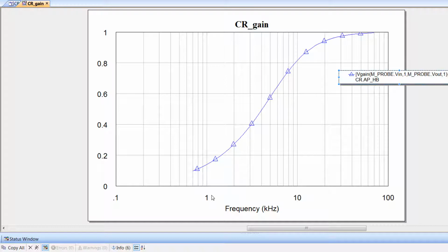Also, you can now see what I meant by a logarithmic scale and a decade. A decade is basically a difference of a power of 10. So we go from 1 to 10, from 10 to 100, etc. And within each decade, normally in the lab, you only measure where there is a vertical line. So you only measure about 10 points per decade. This is how a frequency response is normally worked out.